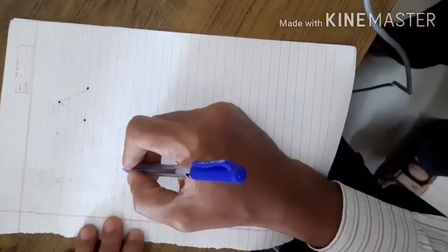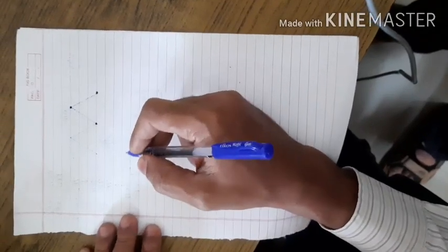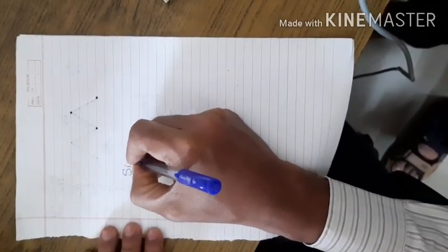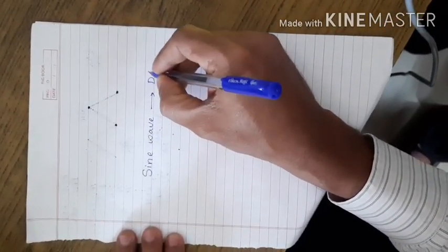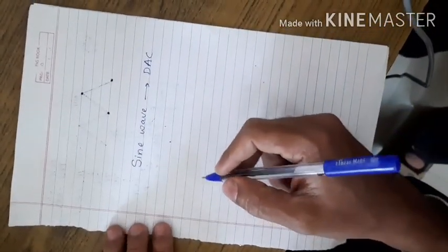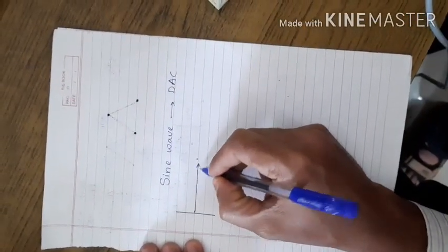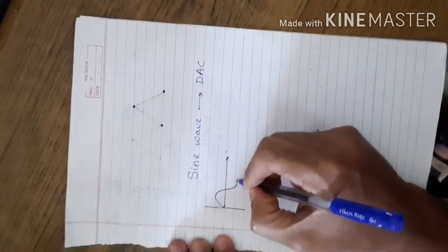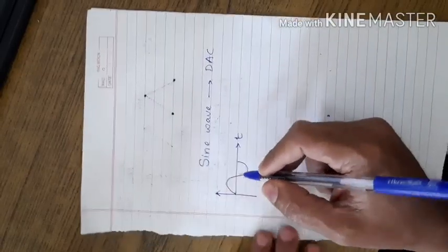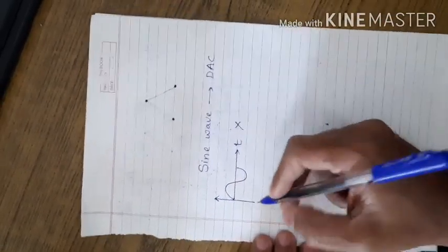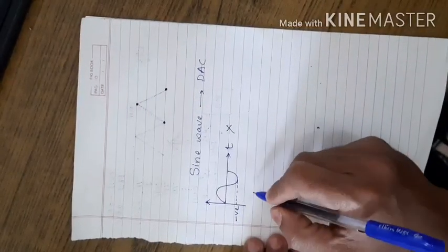Once again we are coming back with one more presentation, a demonstration of how to generate a sine wave, or a sinusoidal waveform, using your digital to analog converter. Now when we speak about the sinusoidal waveform, we know that it will be symmetric about the x-axis, right? But in a microcontroller we will not be able to generate it like this, because we don't have anything called the negative range of the voltage in the microcontroller.